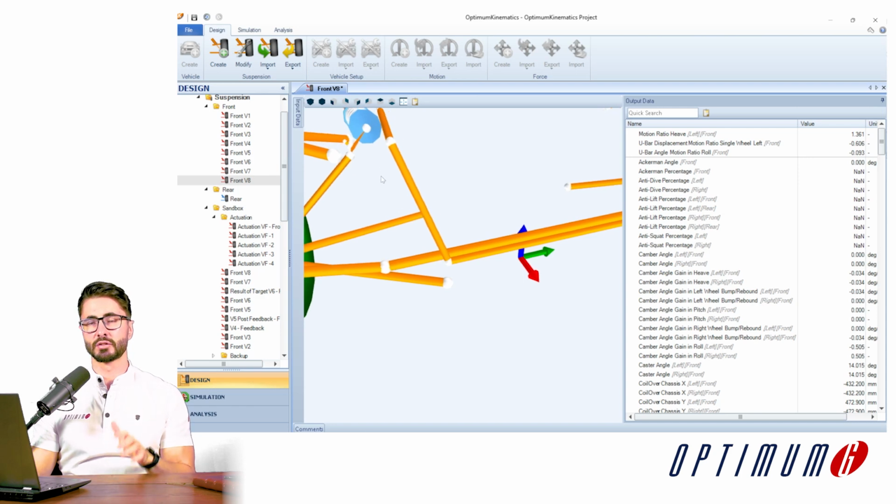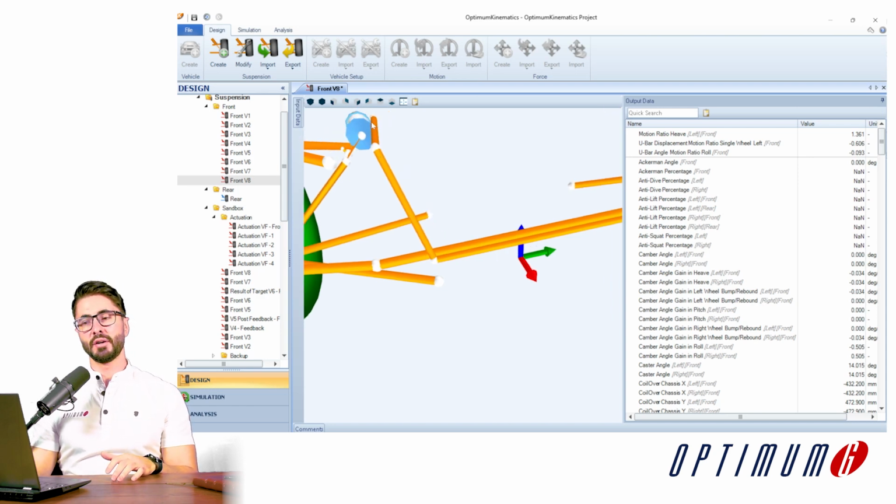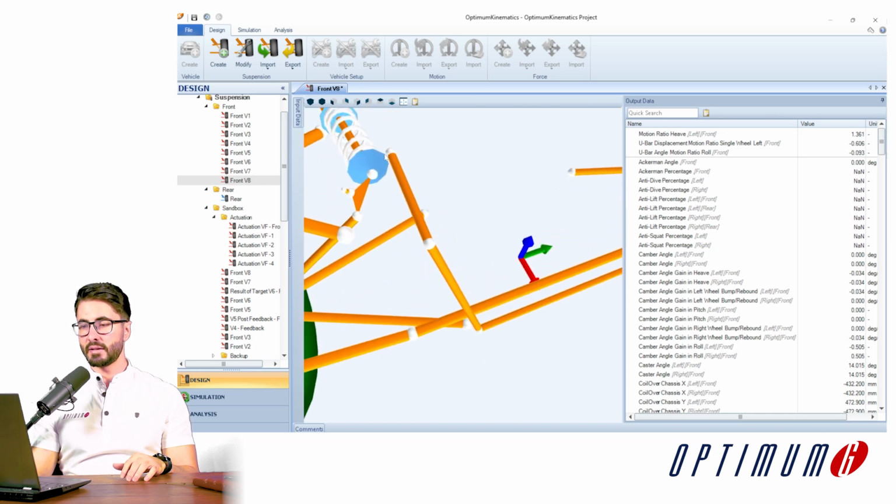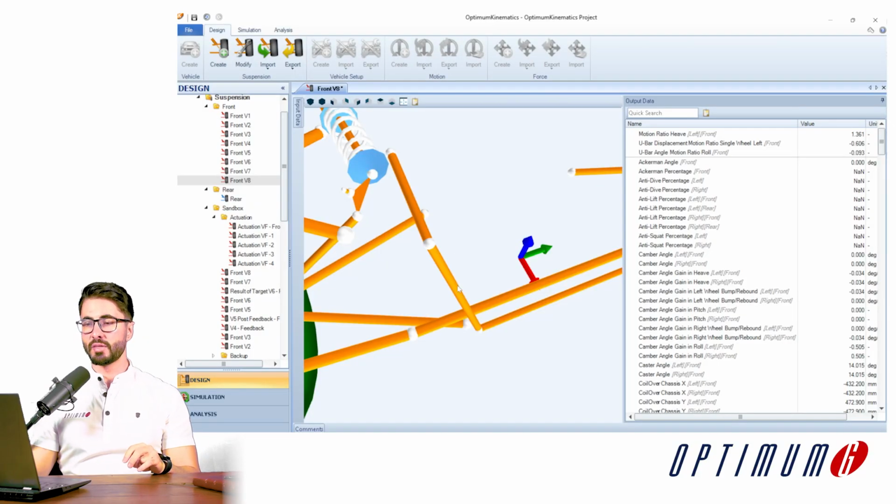The second consideration is the following. Not only do you have to think about this plane, you also have to think about the blade. Because if the forces from the droop link are too out of plane with the blade, let's say that over here we would have a droop link in a completely opposite direction, not only are you twisting the anti-roll bar normally, you are also creating some flexion and some deformation on the blade. So you have to be mindful of that as well.